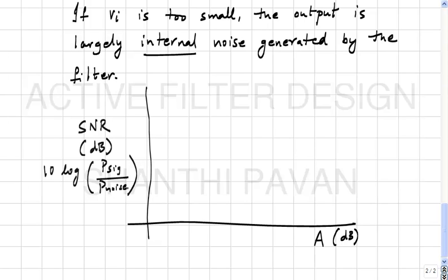In any case, I plan to cover this at a reasonable level so that you'll be able to do something useful with it. We'll figure out how to compute P noise later, but at this point, intuitively, you know that the noise waveform has some power. I'll measure the signal power by the noise power and take 10 log, and that gives me a number in dB as the signal to noise ratio at the output of the filter.